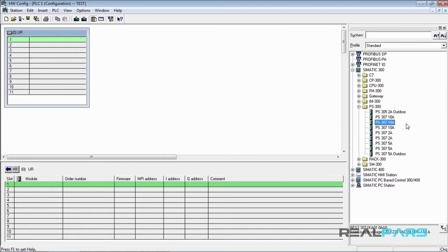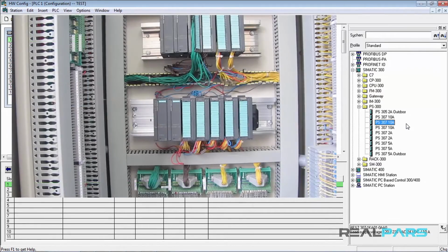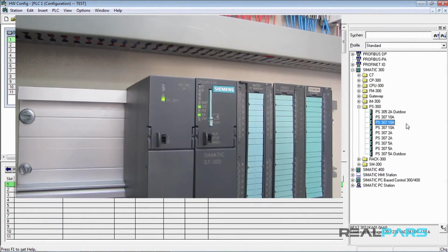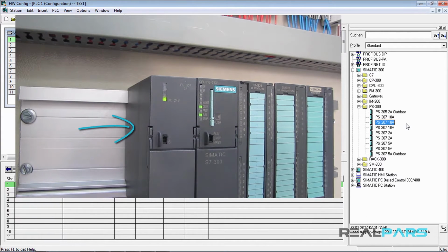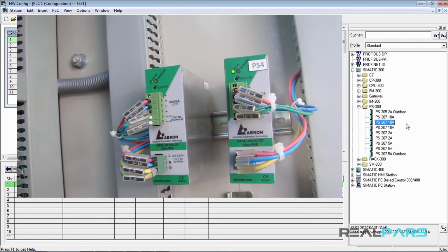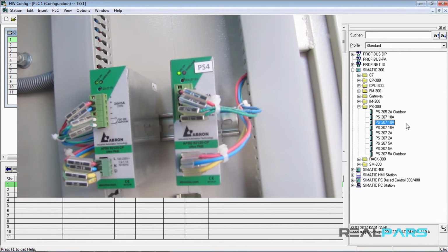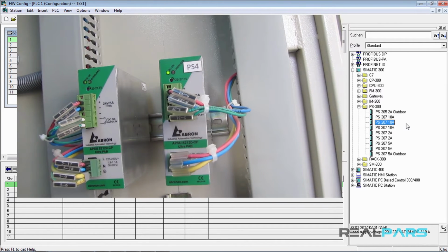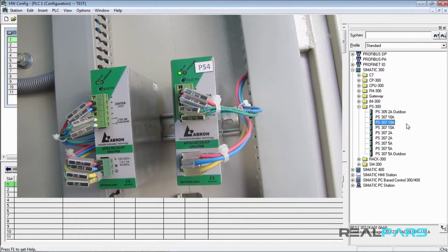In some cases, where we have quite a few facilities in the enclosure, we can use 2 separate power supplies. For instance, we can use one power supply just to turn on the PLC modules, and another power supply for the rest of the facilities and interfaces that we have in the enclosure. Okay, so this is how we choose a suitable power supply for our control facilities.